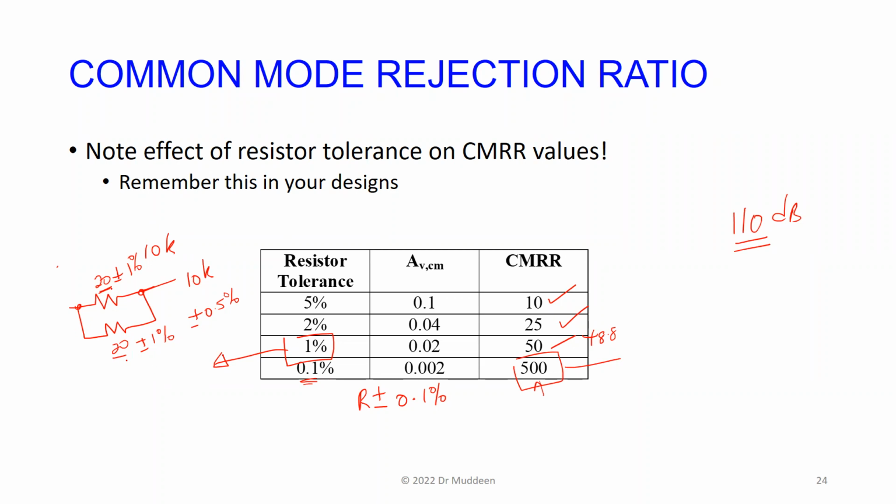And the tolerance, if they were originally 1%, the tolerance of the parallel combination now is going to be at least 0.5%. You're going to get better than 1% by putting them in parallel. This is all about errors, and if you remember when you spoke about these kinds of things in your science, reporting values, and things like significant figures.